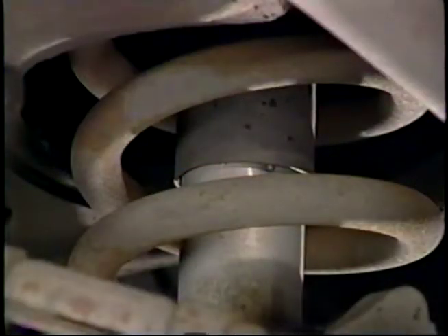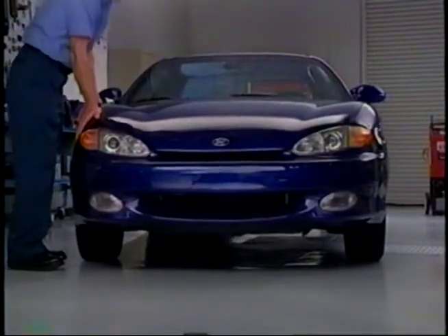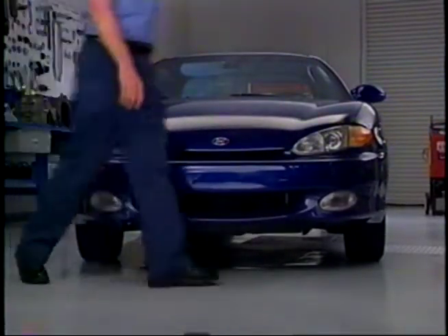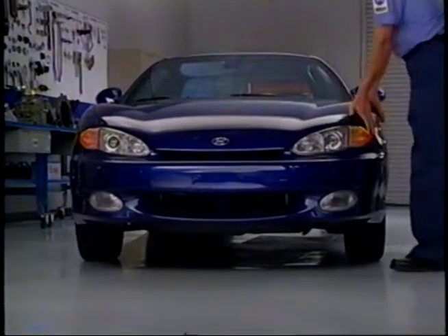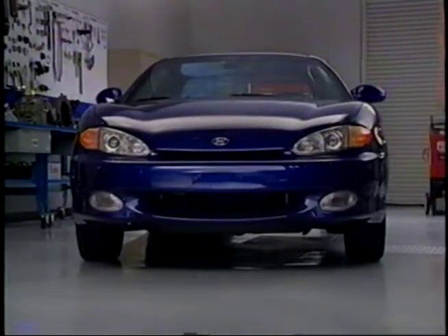Coil suspensions use shock absorbers to keep the wheels on the road. When troubleshooting problems with traditional shock absorbers, use the jounce test. Push the suspect side of the car up and down a few times. Stop and watch the rebound. A vehicle that rebounds more than 1 1/2 times will need to have the shocks replaced.